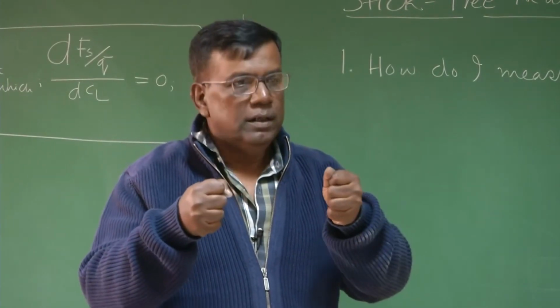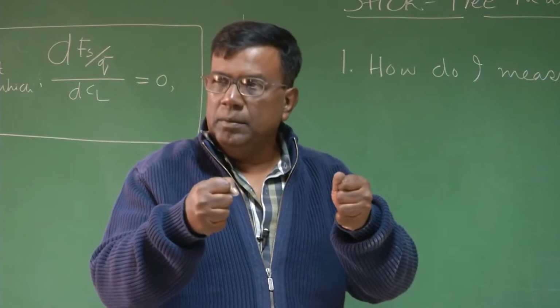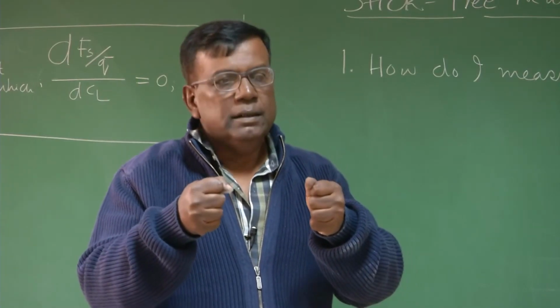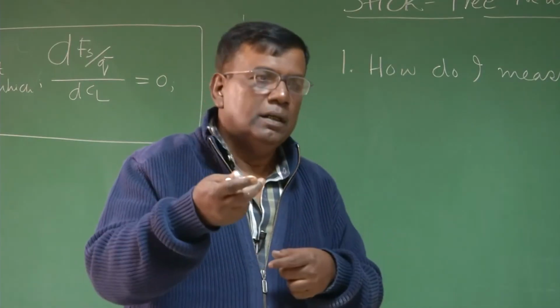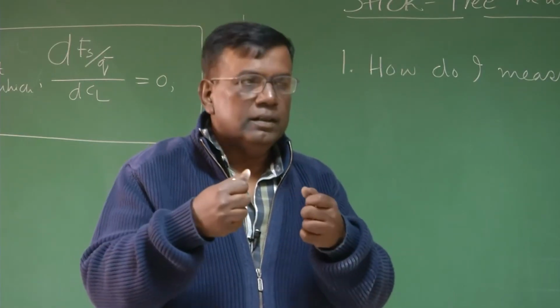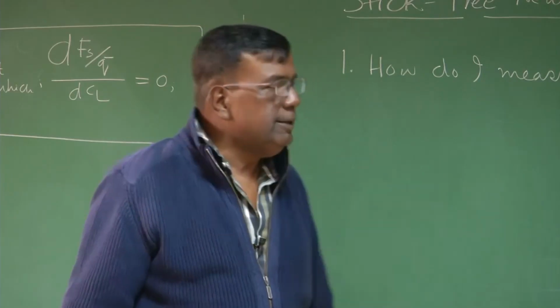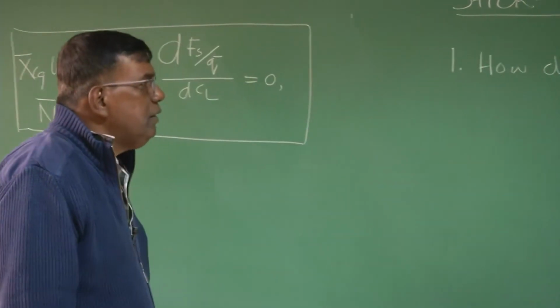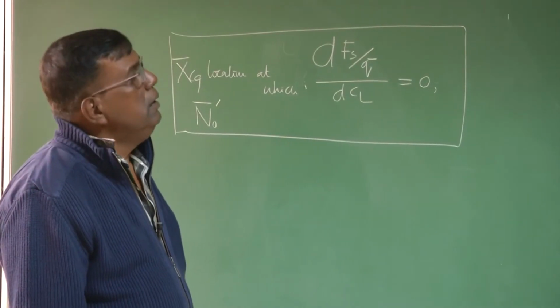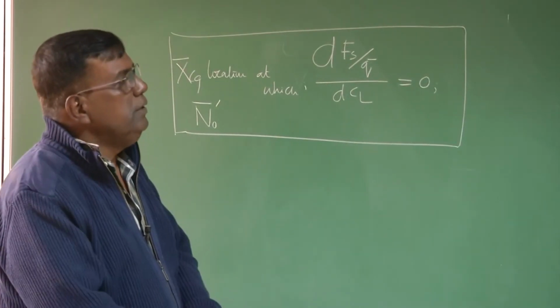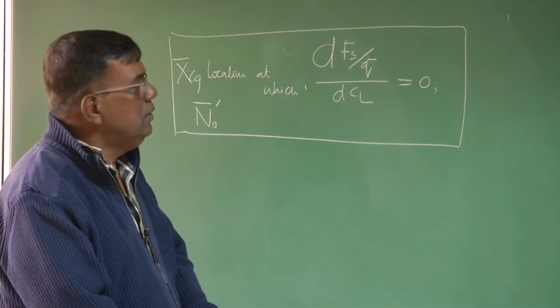As I pull it, there will be bending and stress developed, and through the strain gauge measurement, I can find out how much force has been applied in terms of a pull or a push. So you use the strain gauge principle. You also use a Wheatstone bridge. That is how through strain gauges we measure the stick force.